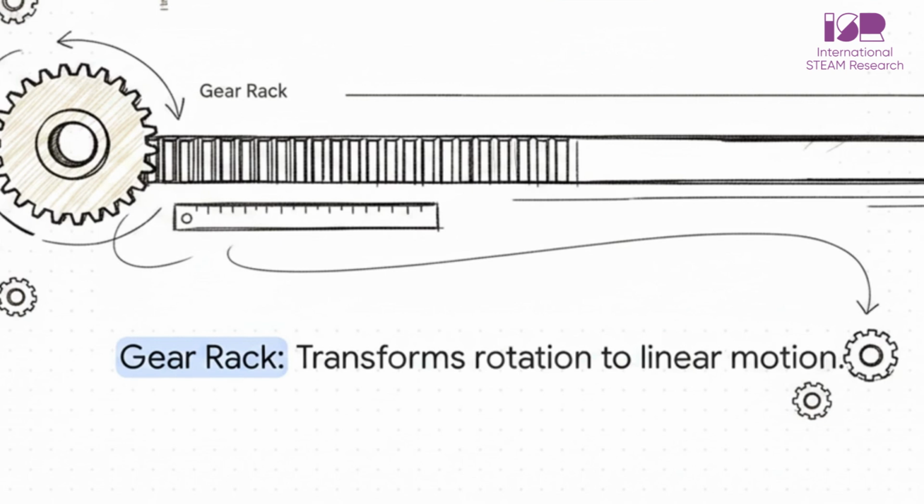By carving the teeth into curved lines, this gear totally outperforms the straight bevel gear in efficiency, strength, and quietness. The downside, they are significantly harder to manufacture. Types 6 and 7 are the screw gear and the miter gear.